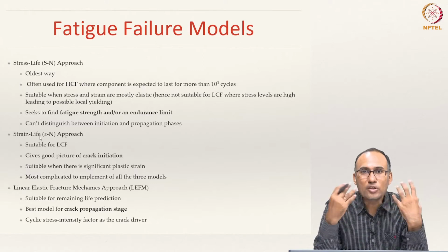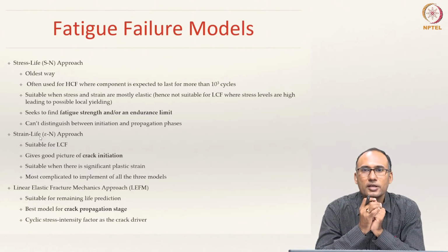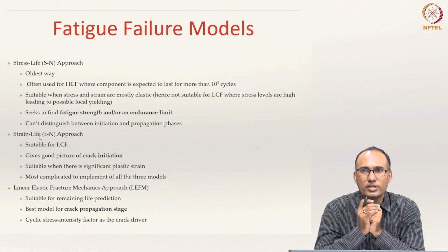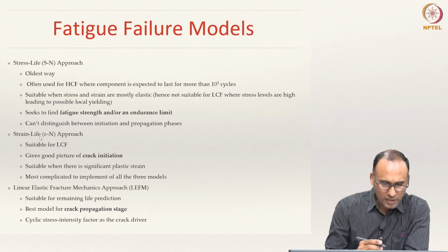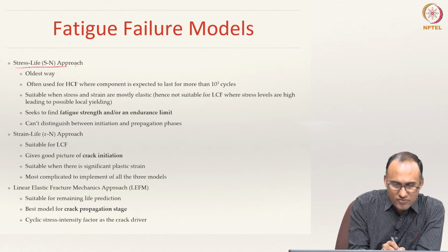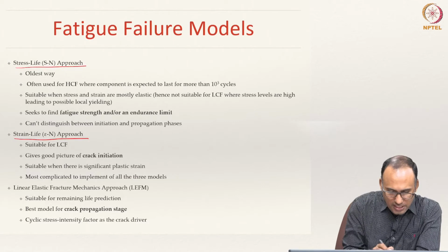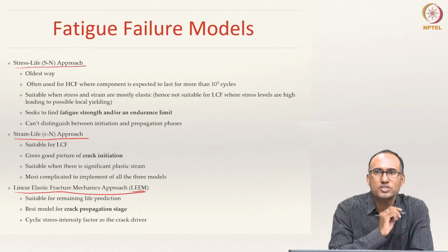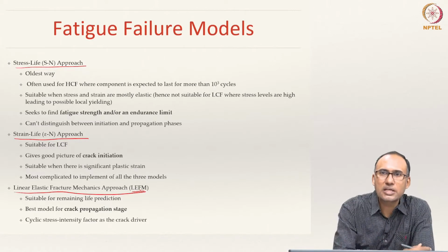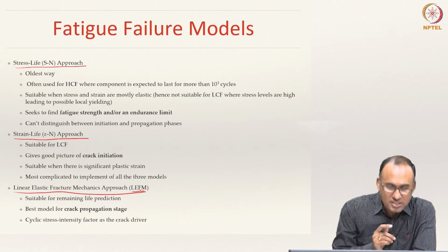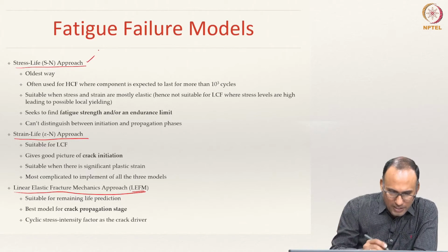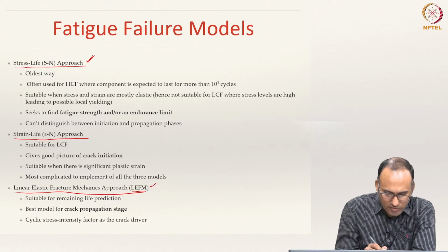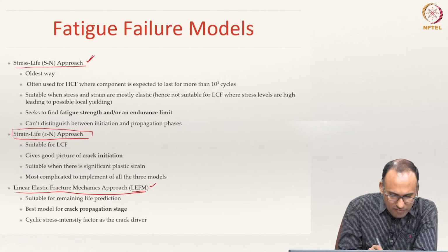What kind of failure model does one need to adopt in order to design components based on the different kinds of loading, right? So here we are going to talk about 3 approaches. The first one is called the stress life approach, then the strain life approach, and the linear elastic fracture mechanics approach or LEFM approach. We are going to talk about these 3 approaches here, and in this class we will study in detail the stress life approach and the LEFM approach, and we will not study the strain life approach.